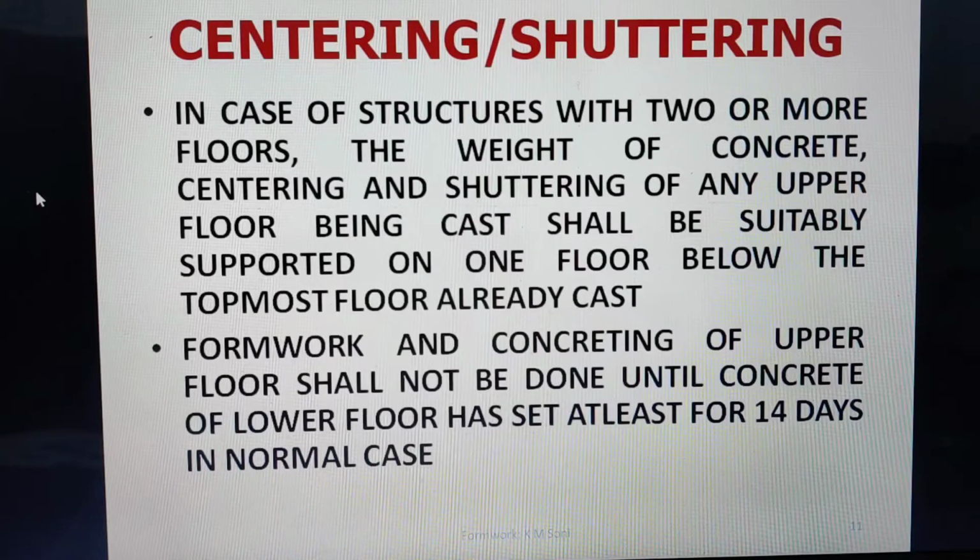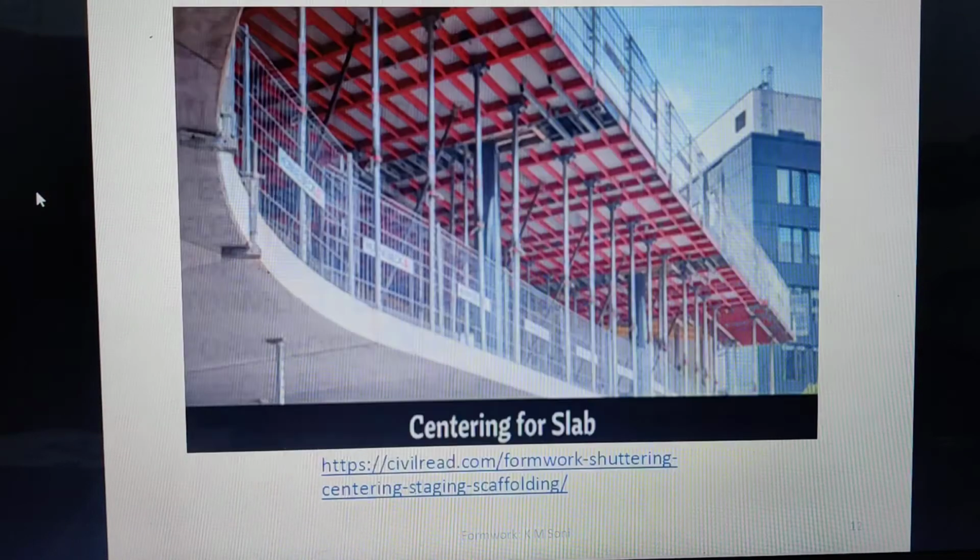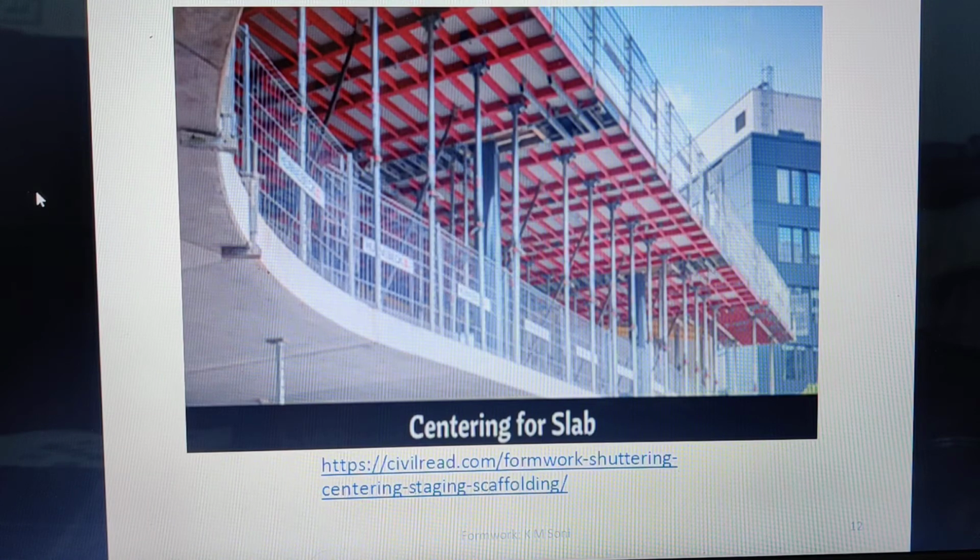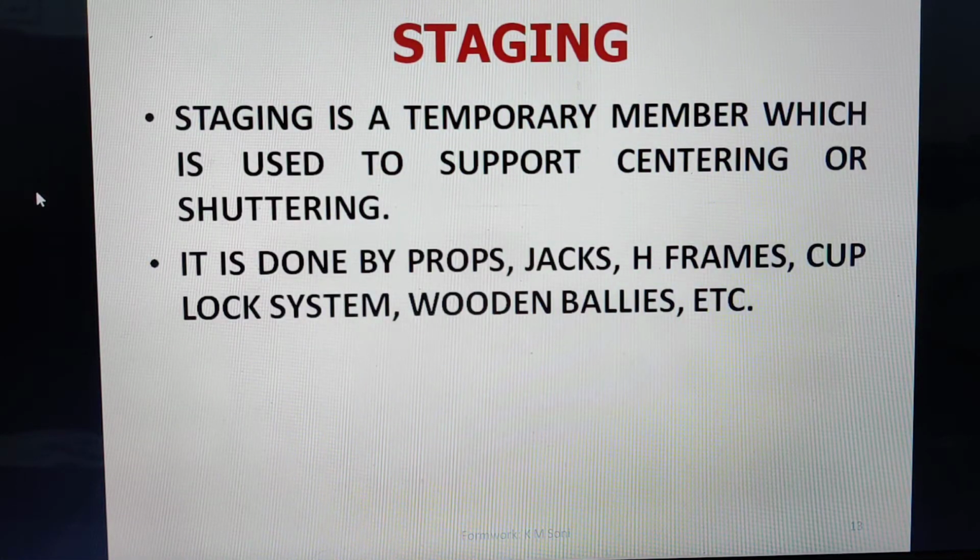And formwork and concreting of upper floor shall not be done until concrete of lower floor has set, particularly in general concrete work, for at least 14 days in normal case. This centering you can see for horizontal portion. Now let us talk about the staging.